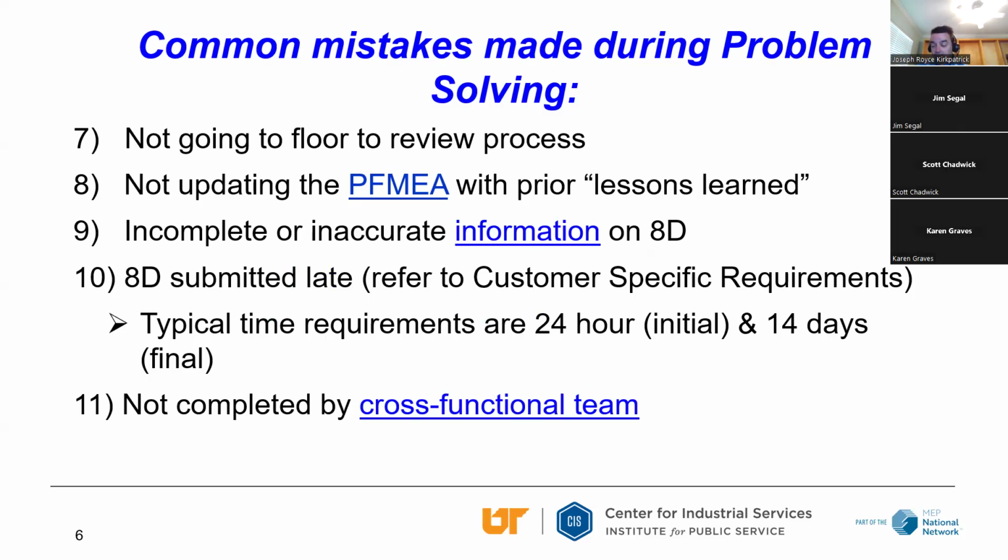Not updating your PFMEA with lessons learned or actions that you're taking to address the problem. Incomplete information on the 8D. 8D submitted late. Some customers require that you submit 8Ds, or at least an initial response, within 24 hours, or 14 days for the final response.